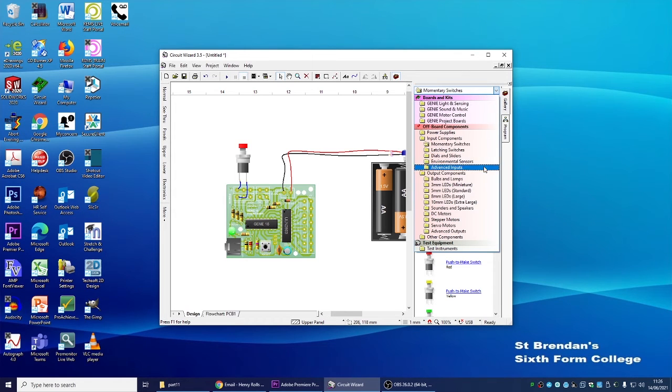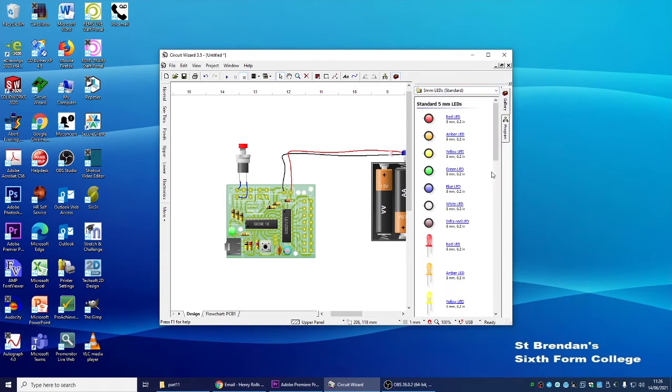So when you use an LED, just beware. These side views are easy to identify: long leg positive, short leg negative, and there's a notch, a smaller bit there. Whereas these ones are not so easy. All you need to do is move it, and you can see there's that flat side there, which means negative. So when you're looking here, all of these are positive, and all of these are negative. So the flat side on the red, I'm going to go to Q0. And then the not flat side goes to positive.